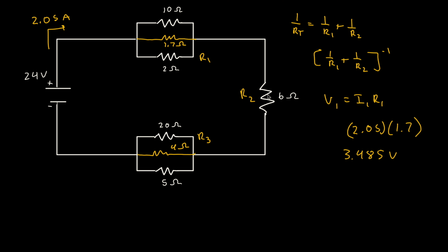All right, so that's going to be the voltage for our resistance over here, the first guy over here. So now let's go to this guy over here. So we're going to use Ohm's law again. Let me label these as 2. So our voltage is what we're trying to find. Actually, what I could have done is just leave this as current total, just so we don't confuse anyone, because like we said, the amount of current flowing through this entire circuit is going to be constant since we are in a series circuit. So over here, our resistance is going to be 6 times 2.05.